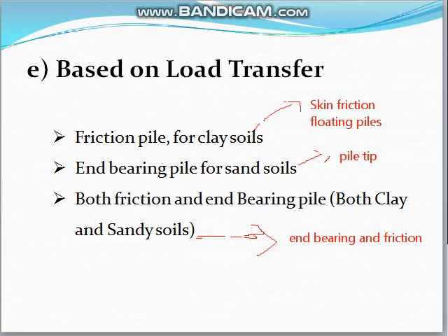In friction pile, load is transferred by skin friction between soil and pile, used when a hard stratum does not exist at a reasonable depth, also called floating piles. And generally for clay soils, this friction pile is used.